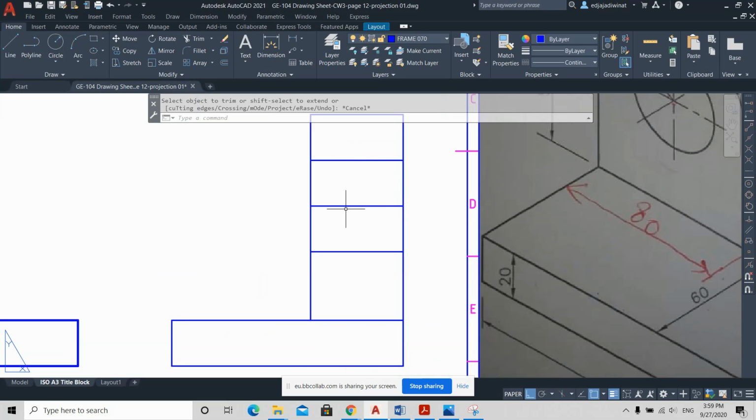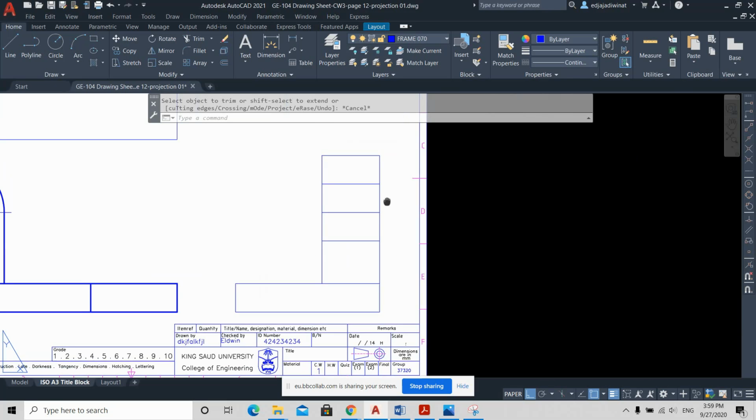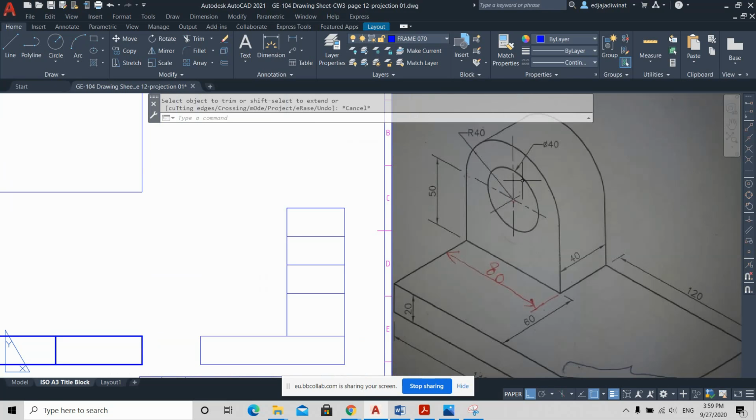Of course, you can offset from here to here. Another way, because the radius is 20, right? The radius is 20, so you can just offset. For example, I'll delete this. I will repeat. You can use offset because the radius is 20, so you will offset this edge to the center by 20. Once you're done, press enter. Is that clear? Until here? Everybody follows? Yes. Okay.